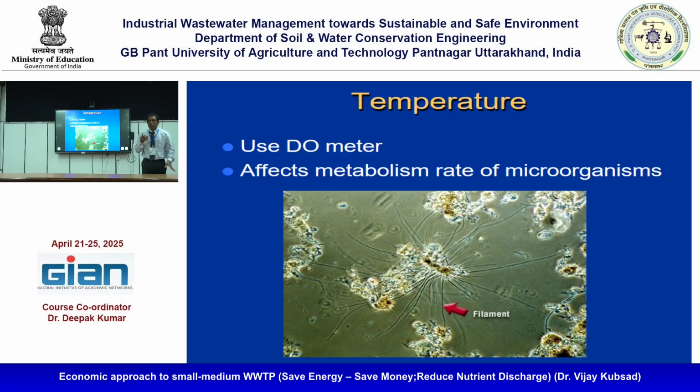Continuous measurements and analysis: why efficiency is reducing, whether any contaminants exist in the sludge, because you are recycling the sludge. So as a researcher, your first question is whether it is treating or it is going through the sludge. That is why you do a sludge analysis, you do a scanning electron microscope, to see what kind of bacteria are there, right? So that we are thinking one step ahead.